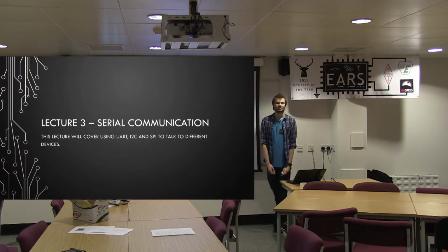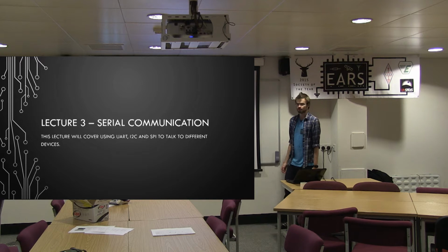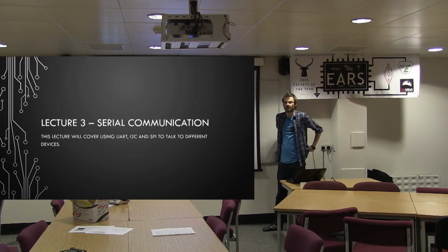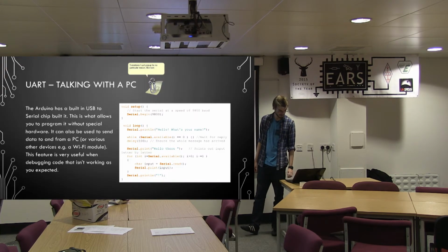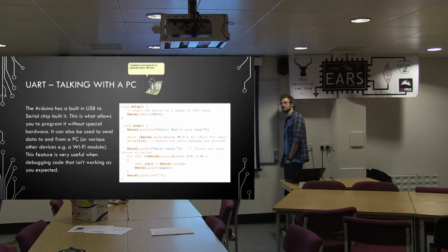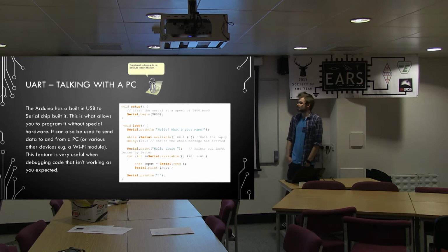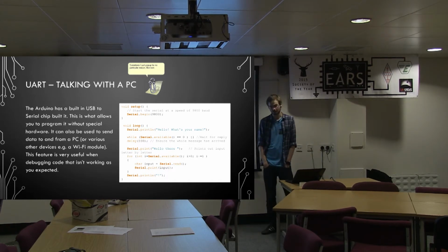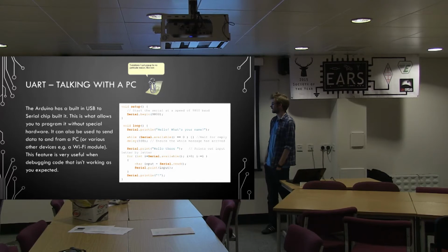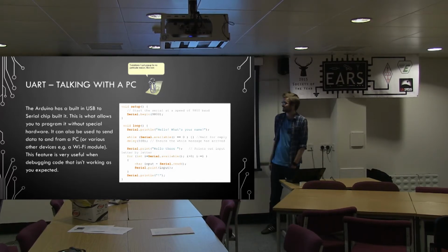Okay, so this week's lecture is on serial communications. So we should be learning how to talk to the computer and to other devices as well. This is basically how you expand the functionality of your Arduino. One of the most important things is talking to the computer. It is an excellent way of debugging, basically. You can make it do more useful things, send data back, and read data in.